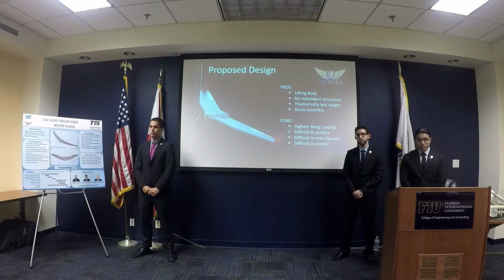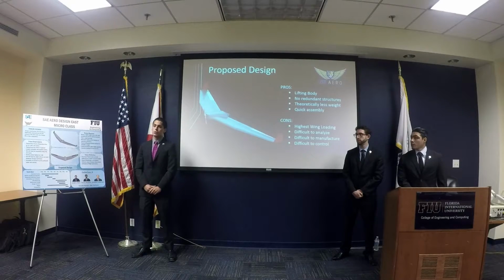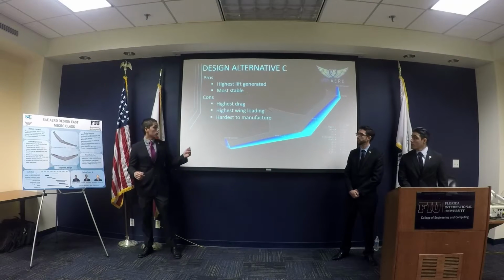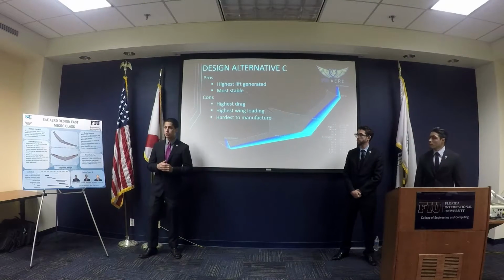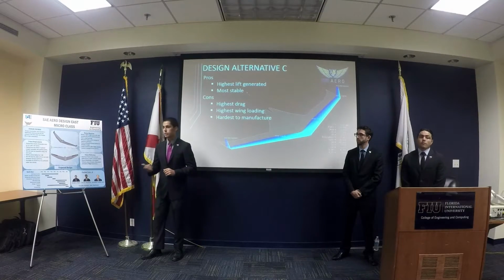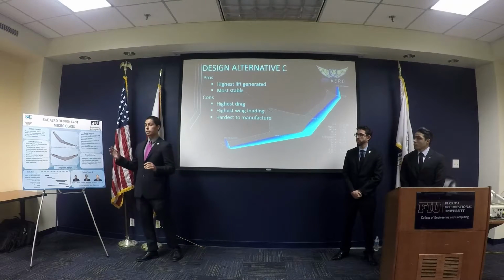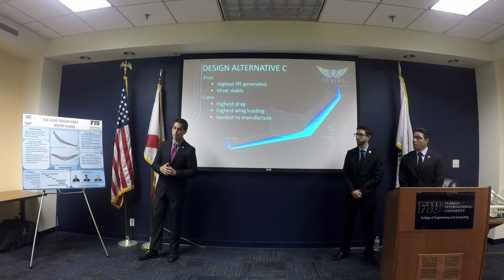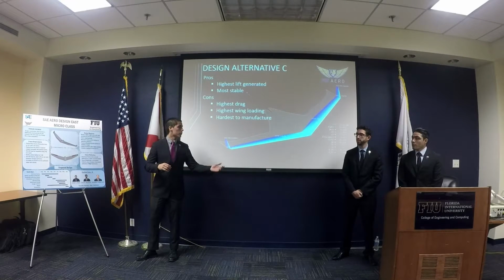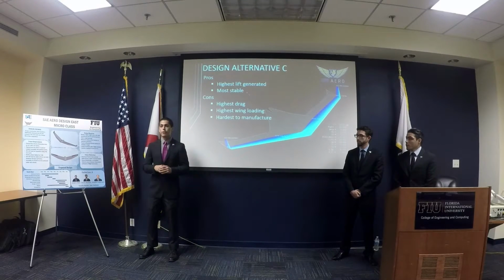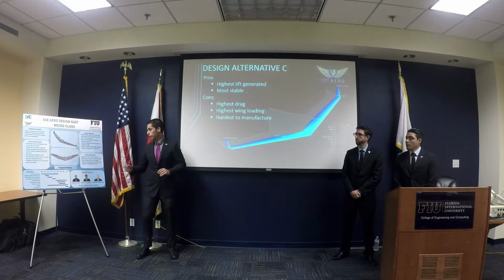So I am concerned that even though your CFD is telling you have a stable wing, your pressure loading is going to give you a different story. Mr. Felix mentioned that he did include 3 different types of airfoils, so you could potentially also increase the stability of a flying wing by adding different sections with different airfoil characteristics. For example, you might want more of a reflex airfoil in the middle.